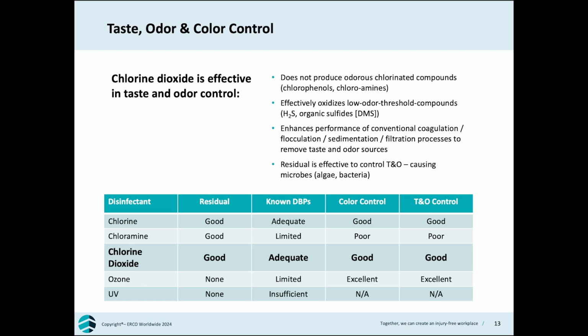Reaction of chlorine dioxide with natural organic matter surface functional groups helps to remove negative charges of colloidal particles, making their flocculation and coagulation much easier, therefore easier to remove by follow-up clarification and sedimentation processes. Again, the residual of chlorine dioxide and or chlorite can prevent algae growth, filamentous fungi growth, or bacterial growth due to the disinfection effect of chlorine dioxide and or chlorite.